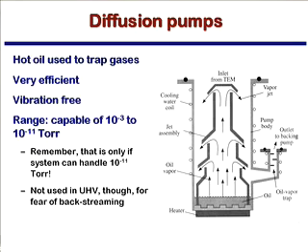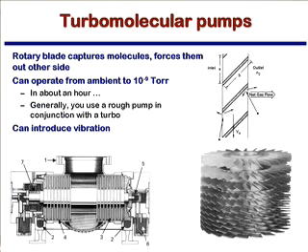And so most microscopes use rubber seals throughout, and can only get down to the 10 to the minus 7, 10 to the minus 8 regime. They don't use copper gasket seals and the like. But again, diffusion pumps usually work pretty well. In those systems where you're trying to get to ultra high vacuum, people just never use a diffusion pump, because if you have backstreaming once, you will basically never get to UHV again in that system. So it's a choice that was made years ago and is increasingly being phased out for the electron microscopy world. But they're still pretty nice pumps for certain applications.